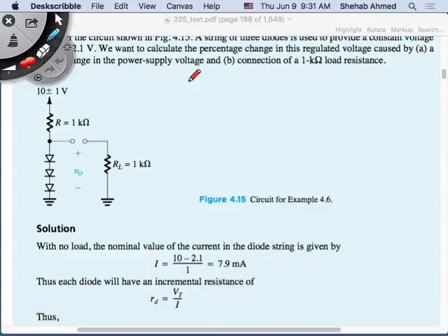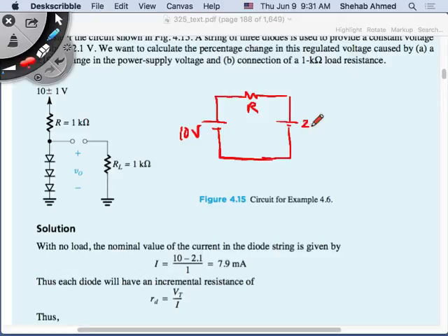So it means I have a circuit that looks like this. This is my resistor R, this is my 10 volts, and this is my forward voltage, 2.1 volts. I calculate the current here as 7.9 milliamps. This is the current flowing in this circuit, so that's my DC operating point analysis. Now I have to do the AC analysis to look at the effect of the plus or minus 1 volt ripple. Correct? How do you do that? You take your 10 volts as well, same resistor.